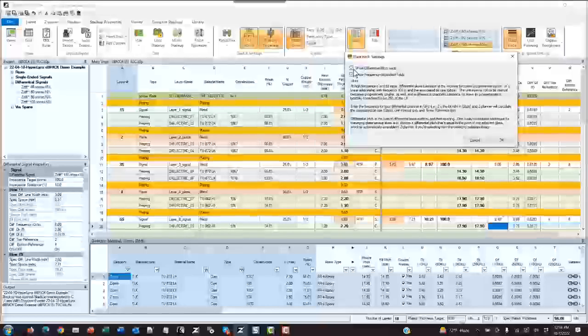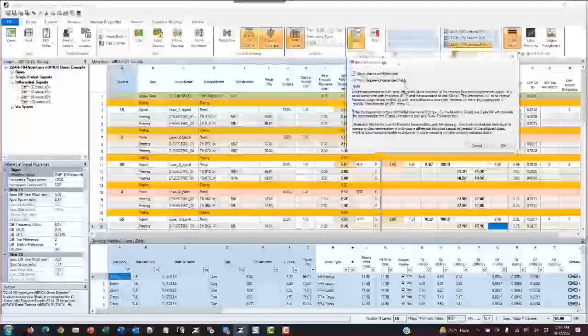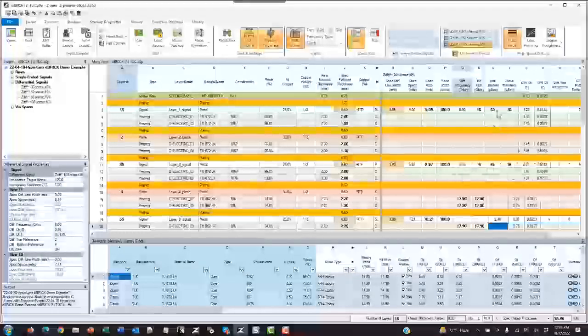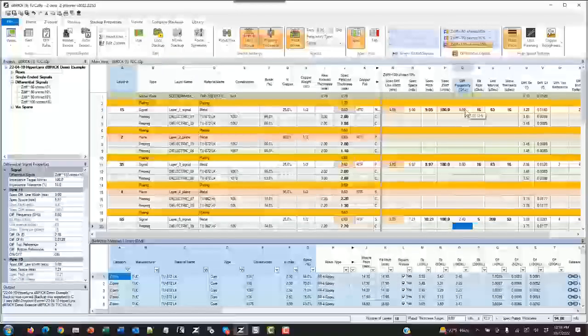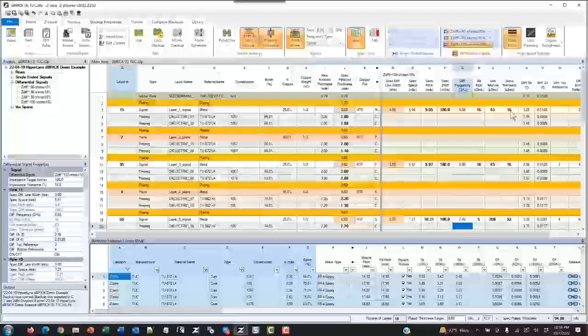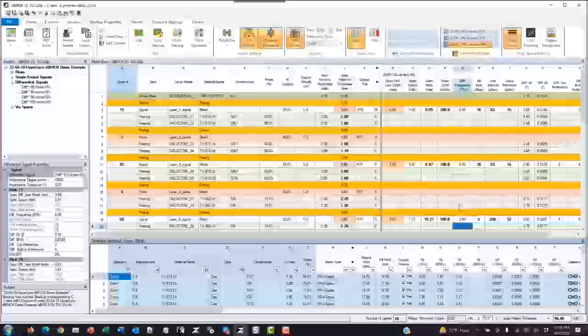I'm also going to turn on glass weave skew settings. So when I open this dialog, I'm going to turn off differential pitch. And what we'll discuss both in the tutorial that I pointed out to you and in the next webinar is why the differential pitch for the signal and the pitch for the underlying weave, the glass, matter. How those correlate to each other matters in terms of controlling glass weave skew. But I'm going to turn off those fields for now, and I'm going to switch to frequency dependent fields, and you'll see some numbers that correlate to one of our previous slides. So I've got 8 gigahertz, 16 gigabits per second for PCI Express 4, a calculated unit interval, and then a 25% skew tolerance. So this is all at your fingertips within the software.